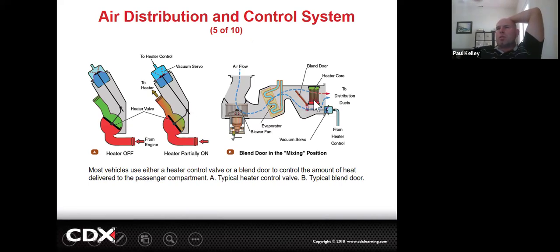We're using a temperature door. So here's your blend door, your temperature door. Cool. Now, how is this one controlled? If you look, this is a vacuum servo. And by the way, it's not all the way open or closed. You could have it be blended, therefore the blend door. If your AC is blowing really cold and you put it slightly to warm, you can actually mix a little bit with the heater core and get not freezing cold, ice cold AC. You get slightly more warm, right?